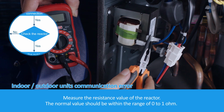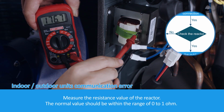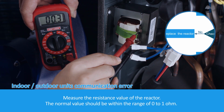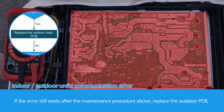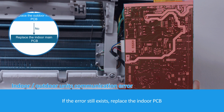Measure the resistance value of the reactor. The normal value should be within the range of 0 to 1 ohm. If not, replace the reactor. If the error still exists after the maintenance procedure above, replace the outdoor PCB. If the error still exists, replace the indoor PCB.